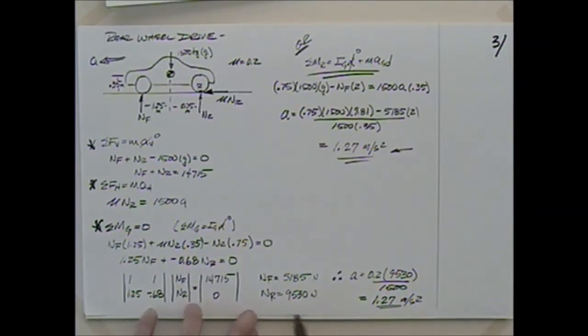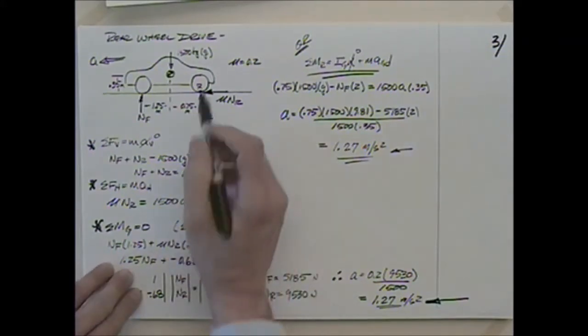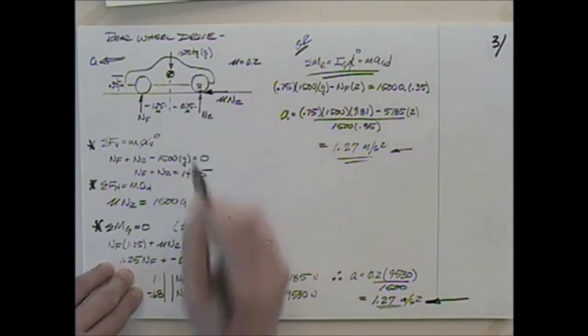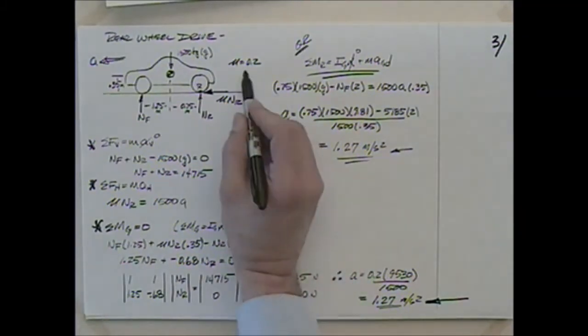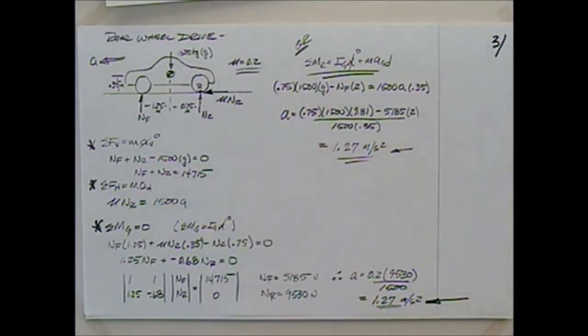So I think we came up with these values, and we came up with a much smaller acceleration, and then we had to try and rationalize that. Would we be able to get to that 2g acceleration if our maximum acceleration based on friction is only a fraction of a g? We wouldn't, would we? We'd start to break traction. We'd start spinning the rear wheels a long time before we pulled the front wheels off the ground, right? And I'd mentioned that the coefficient of friction, 0.2, is very low. That'd probably be if the track was iced up.